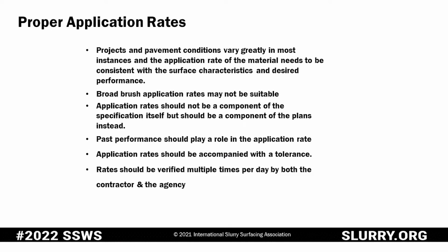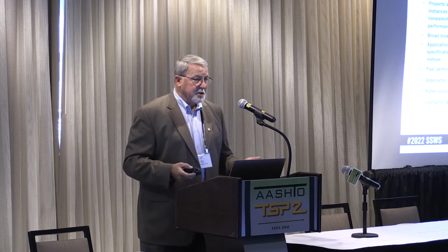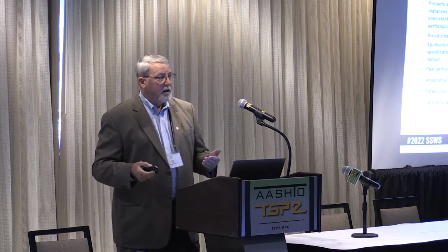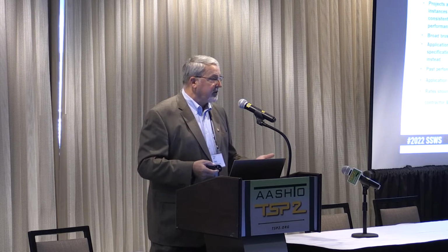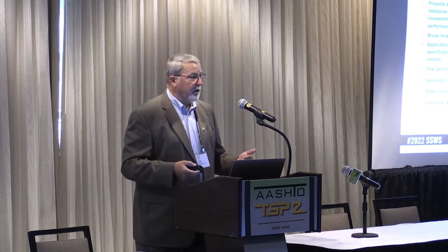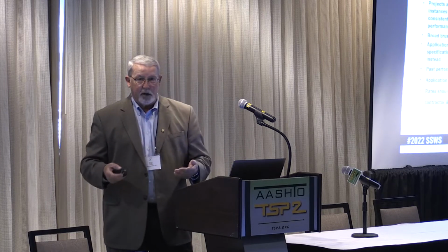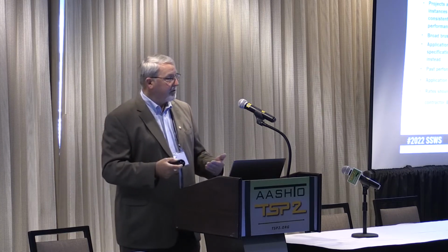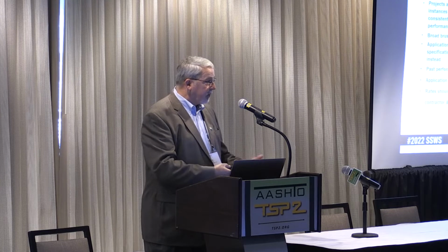And the rates should be verified multiple times a day by both the contractor and the agency. With today's equipment and the monitors out there, you can get real-time information by just turning around and looking at the monitor on the machine that will give you an indication of what your current application rate is at that time, in real time.